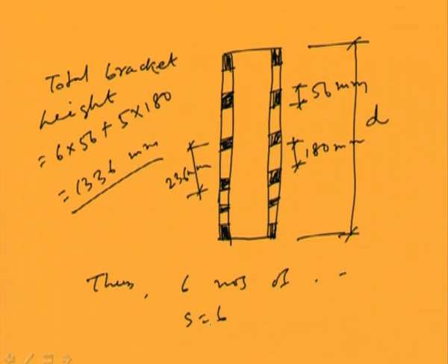So the answer is, when it is asking to design the joint, that means we have to make the detailing of the joint in terms of the length of the intermediate weld, spacing of the intermediate weld, the number of intermediate welds, and the total height of the bracket which is required to make the welding, right. This is another type of example that I have shown here.